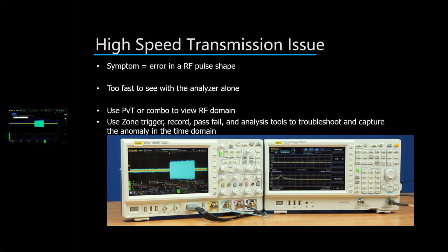So really able to look at different patterns in frequency and embedded code to really see all the problems that might be happening and how we can then go ahead and debug them. So here, if we go find one of our failures, we can see a couple things. We can see what frequency that pulse came in at. We can see some of the modulation on it. We can also see down in the digital line an error seems to be happening on D4, right?